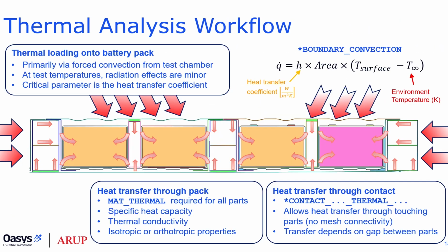So this slide summarizes the workflow in LS-DYNA for the thermal analysis. To model the thermal loading onto the battery from the forced convection in the test chamber, we can use the boundary convection keyword, which requires us to provide a temperature time history and a coefficient of heat transfer. This controls the power available to heat up the outside of the battery.